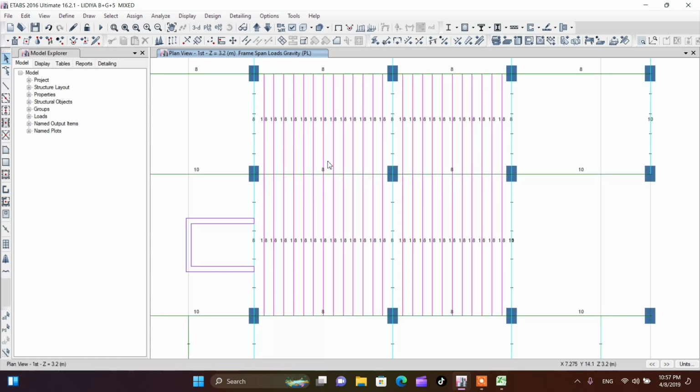So all the partition wall load on each rib is assigned like this. You can do it in a similar way for live load, by multiplying the live load, that is 2 kilonewton per meter square for internal partitions, by the spacing 0.4. You assign your girder beams by selecting the edge and calculating the load, and you can design in a similar way.